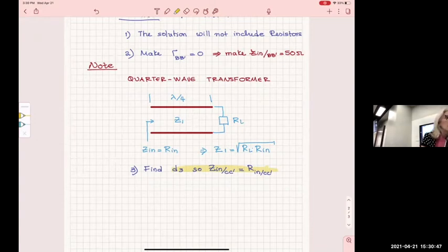Okay. What determines whether something is lossless or not? The materials themselves. Okay, so Z1 isn't solely dependent on... Z naught only depends on the geometry. But in real life, everything is lossy. All of the materials will have some kind of loss. All of the conductors will have some kind of loss. The thinner the conductors, the more the conductor loss. You have to make them very thick to avoid that. Who wants to put thick gold or copper, which is extremely expensive?